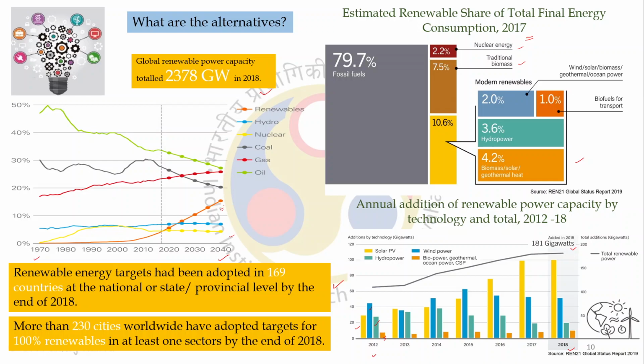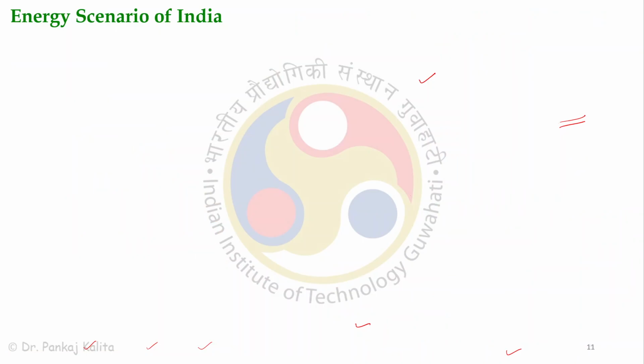Okay, you guys are understanding now. So in night we don't have any sun. So whatever power we can produce is in the 8 hours of the day. So its capacity will be one third of the total capacity, compared to a coal power plant. Coal power plants generally have high capacity factors.